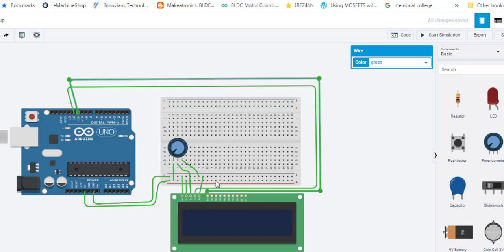Okay, now I'm going to connect all the other pins. This LED cathode should be connected with ground, and one resistor should be connected over here in between other pins, that is, pin 15 should be connected with a resistor. So I'm going to use one resistor over here with 5 volt. Anyway, I can connect.